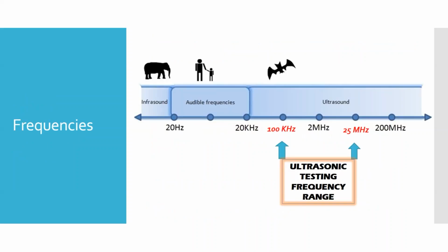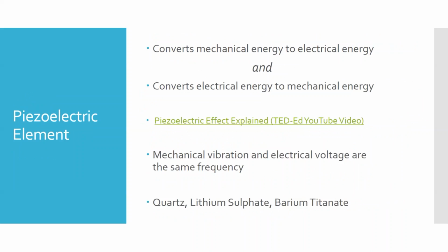So we looked at ultrasonic testing frequencies, again, compared to our audible frequencies, where we're looking at 100 kilohertz to 25 megahertz. And I talked about what these piezoelectric elements are. I've got a video that shows it more than just the explanation I provided. Okay, so the quartz that they talked about in the video is one, but we can also have lithium sulfate, or probably what's most common for ultrasonic testing, barium titanate.